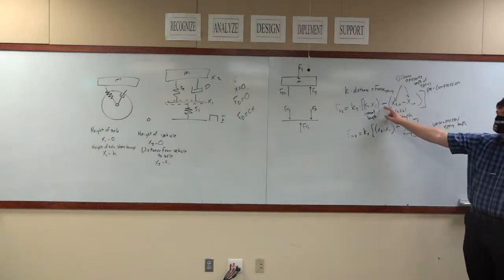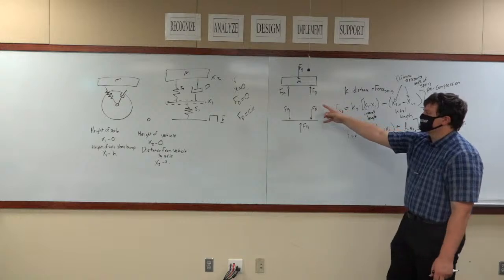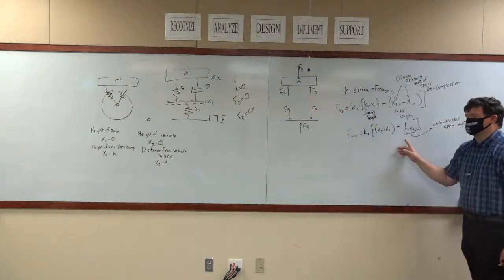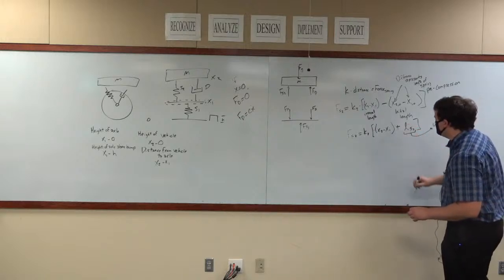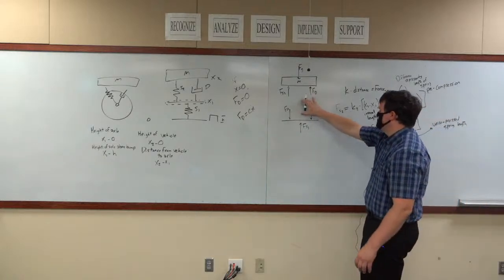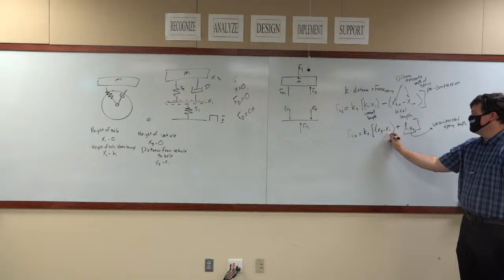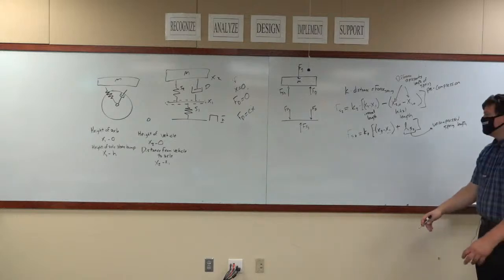The way that this is written is if the spring goes in tension, the number is positive. If it goes in compression, it's negative. We drew ours in compression, so we have to switch those signs. Does that make sense? Just trying to make sure that we get a positive value when we're actually getting a positive value. Okay, so that's the spring force for FS2. This does have two variables in it, which is kind of gross. But that's what we have to deal with.